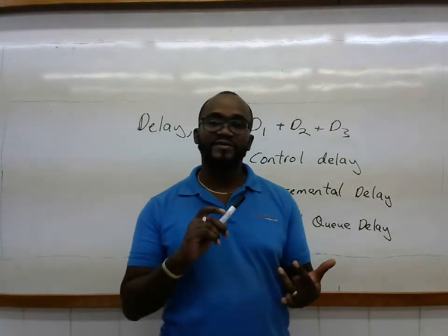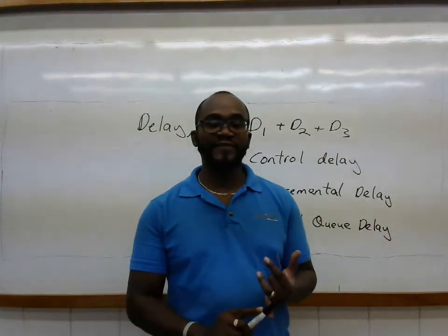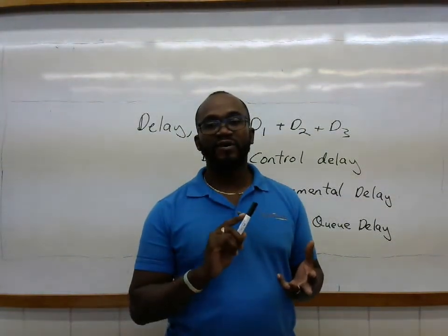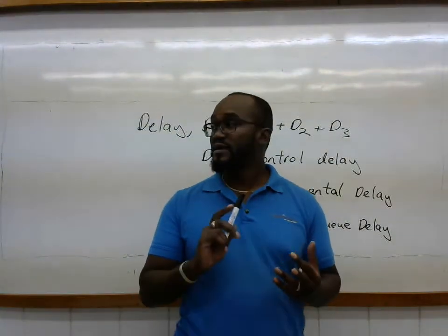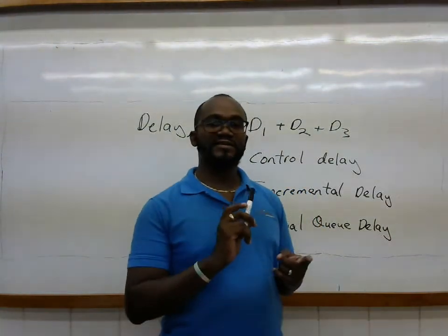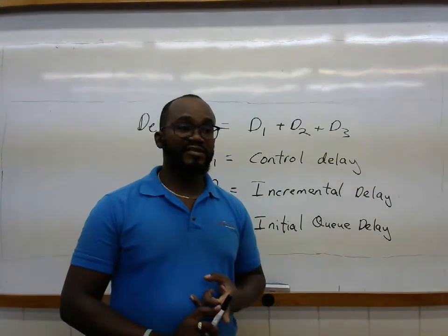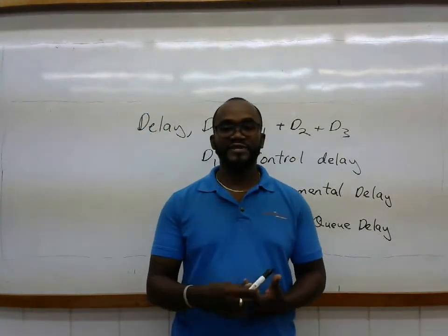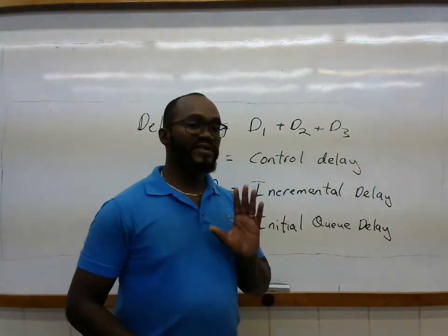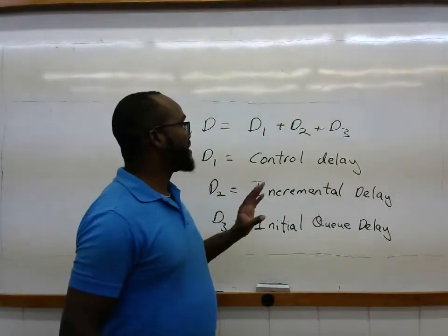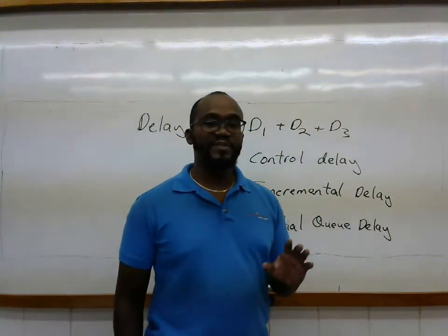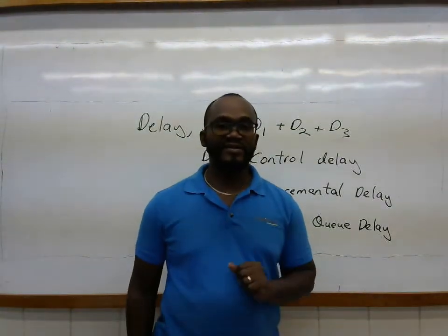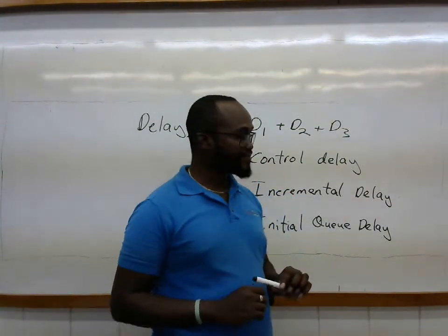So you have level of service values, for example, on freeways, for unsignalized intersections, two-way stop control intersections, four-way stop control intersections, and you even have level of service thresholds for pedestrians and cyclists. So just to be sure that we're on the same page, the calculations that we are doing for the purposes of the coursework are specific to signalized intersections.